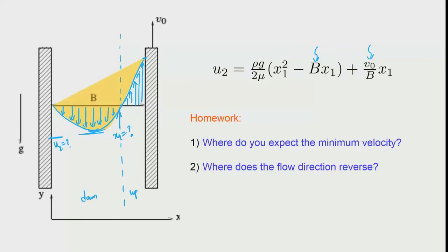So, we could go further by taking more and more terms, but at this moment we have already done enough to check how the variation of velocity profile would come out. So, basically we are looking at solutions that are coming from only the diffusion term, okay, and only one at a time, and we are then getting the solutions in a simple form, and you can see that the solution is applicable to the entire domain, okay, and this is something that we are going to relook later on, whether this is reasonable or not, but at this moment the diffusion profile is applicable to the entire domain, and that requires the laminar assumption to be valid, and that is the reason why we want to look at the critical Reynolds number, so that the solution is valid.